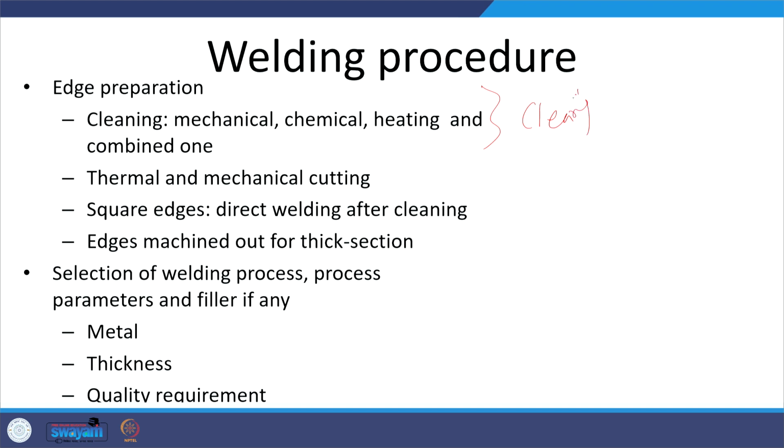So, the cleaning can be done using chemicals or using mechanical methods like wire brushes or polishing papers for removing the rust. Chemicals are used for removing all organic compounds like oil, paint, etc., if they are there, or we can club the mechanical with the chemical cleaning for more effective cleaning.